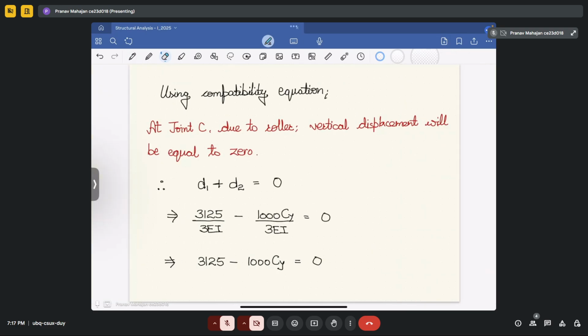After that, we have seen one problem related to force method, in which we are provided with a propped cantilever beam subjected to a point load at the middle of the section, and we have seen how to solve that problem. We started with finding out the static indeterminacy of the whole structure, and we found that it is equal to 1. That means we have to remove one unknown force from the whole structure to make the structure determinate.